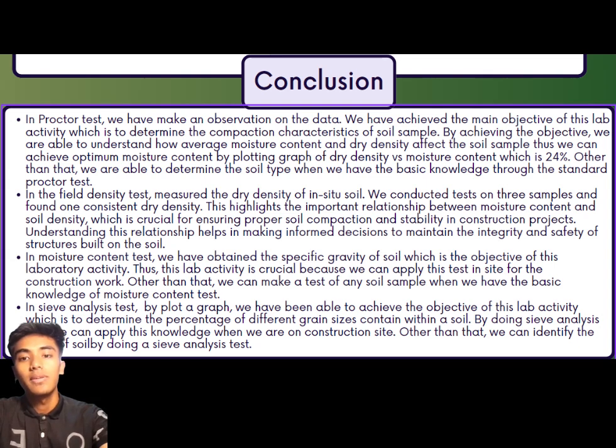Lastly, the sieve analysis test enables us to determine the percentage of different grain sizes in the soil by plotting a graph. This test is essential for identifying soil types and understanding their composition, which is critical for construction site assessments. The ability to perform a sieve analysis test allows us to classify soils accurately and apply this knowledge in real-world engineering projects.